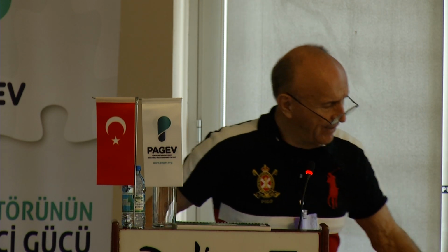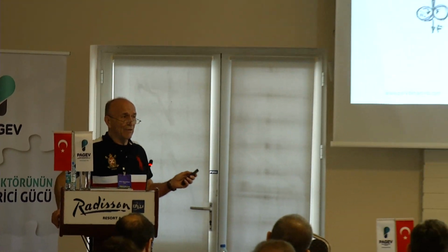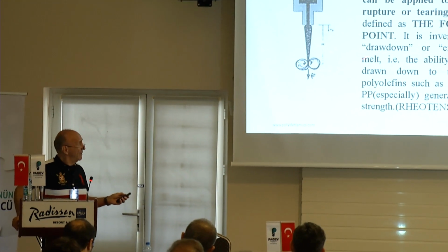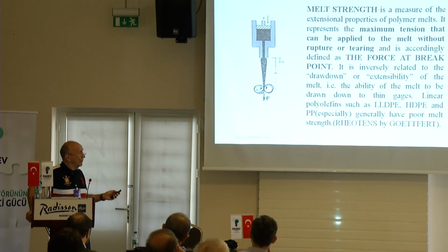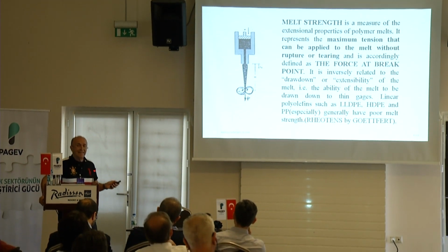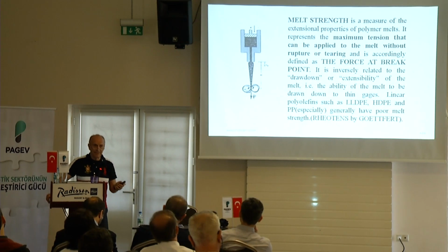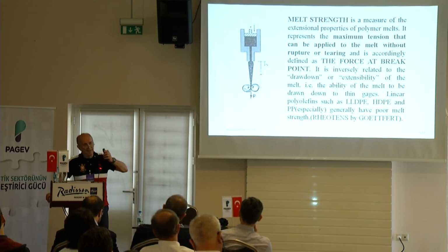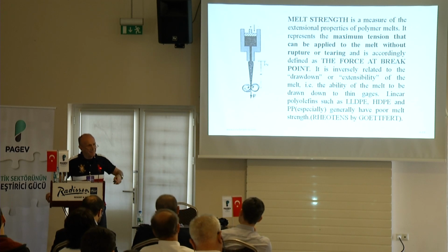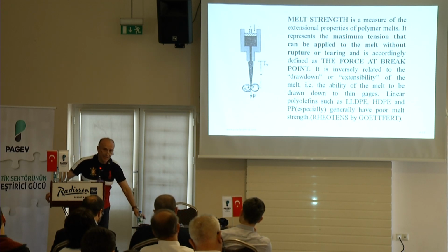And you have a contraption like this: you stretch a strand, an extruded strand of a polymer, by a pair of rotating rolls till it breaks. And the force required to break the strand is the melt strength.